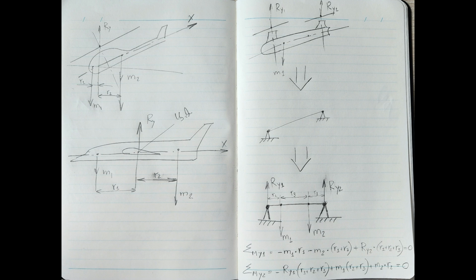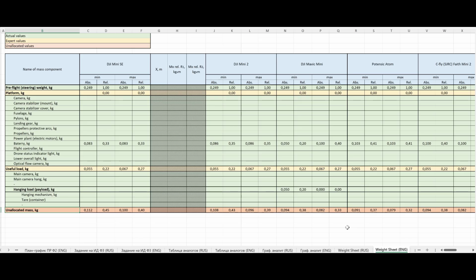If the helicopter is positioned symmetrically relative to the plane of symmetry and its electric motors are projected onto conditional frame points, which are the hinge points of support in our scheme, then we obviously get different loading at these points from the payload and fuselage. I.e., from the point of view of economy, we should choose two types of engines and two types of props. However, I have not encountered this even in cargo drones, domestic and foreign, that can be adapted to a given payload. I.e., even in them all the rotors are the same.